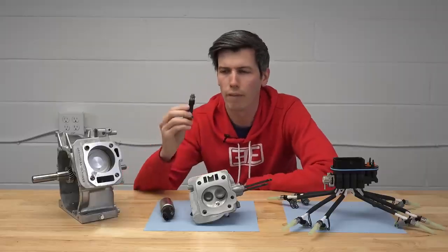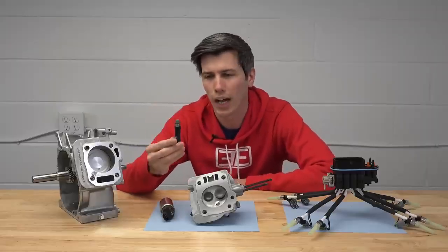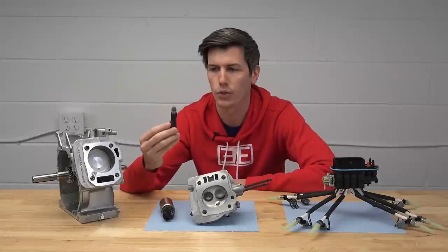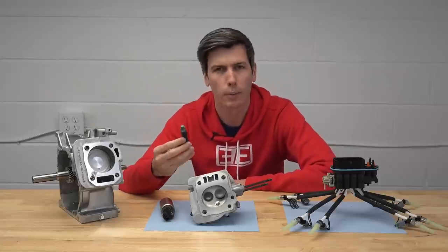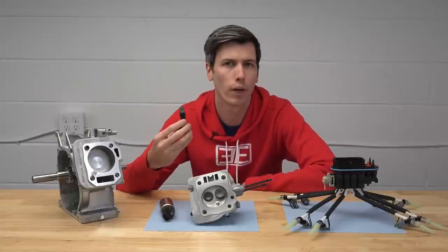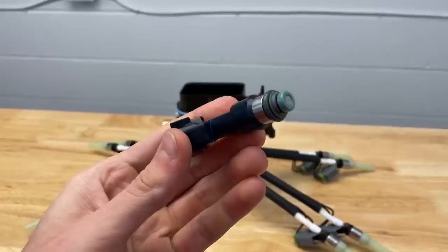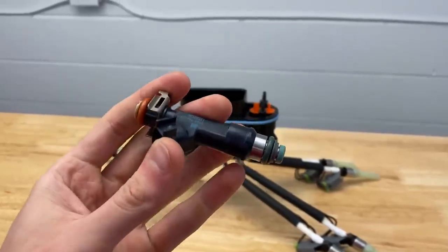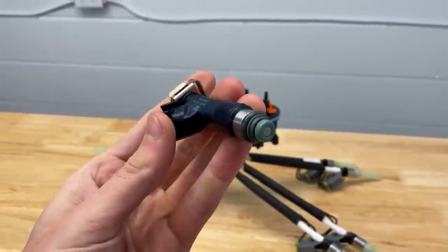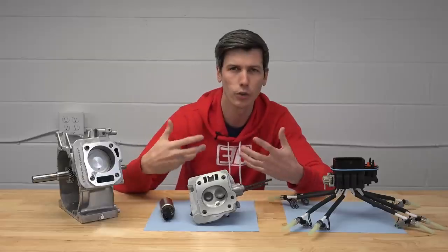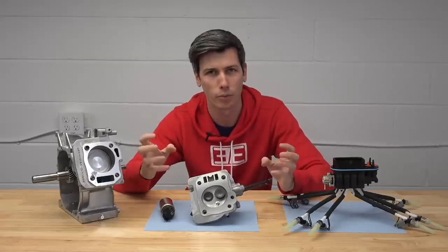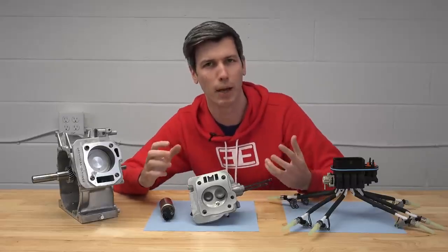So the big advantage of port injection is you have control over timing and how much fuel you're actually going to inject. So for example, if you want to make lots of power, well, you'll run a rich air-fuel mixture, meaning you have excess fuel. And you do this for 2 reasons. First of all, by dumping in that excess fuel, it ensures you're really going to get most of that oxygen within the cylinder burned, so you're going to make as much power as possible.